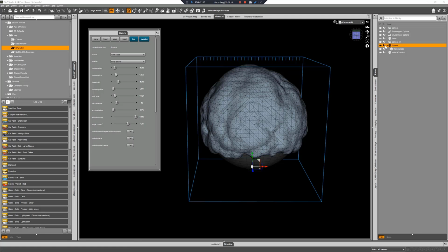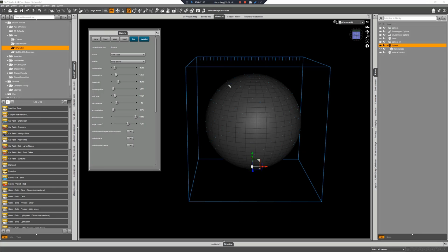Okay, then we have the blob size. I was drawing something to explain what a blob is. A blob is basically a virtual sphere growing around each particle center, and these spheres are later connected to each other by the algorithm which evaluates each of these spheres, called blobs, and by connecting each of these blobs it is going to generate the final mesh, the final geometry.